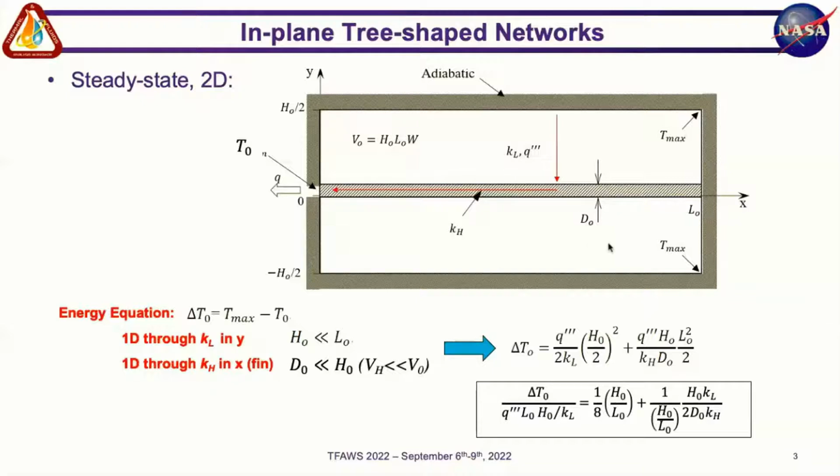But we started here with the simplest one. The simplest one is just to get a straight amount or a straight conduit of this material right at the center. And by doing that, because of symmetry, then you can achieve a strong reduction of maximum temperature in the corners. Now, for instance, when I first saw that, I said, well, why don't we do a diagonal placing of this material right from the heat sink point in here to the point of maximum temperature on both sides and distribute this material in two straight paths?